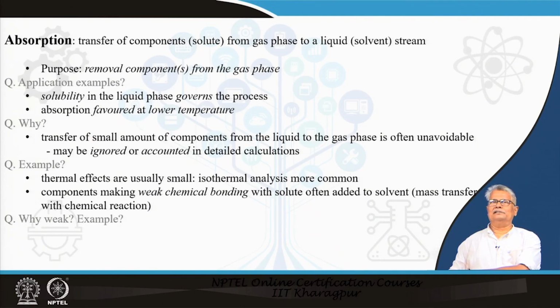Now, it is not so that all my absorption processes will have only one-way component transfer, that means from the gas to the liquid. Often in real systems, you will find a part of the solvent would vaporize, or if the solvent contains more than one component, one will be vaporizing compared to the other, and there will be a small amount of transfer from the liquid to the gas phase also. This in fact is inevitable in all practical processes.